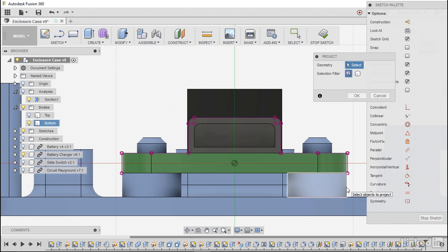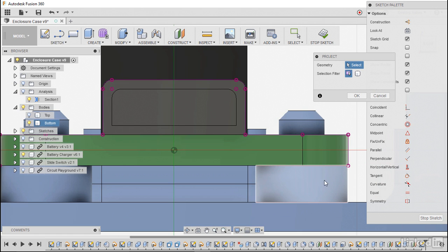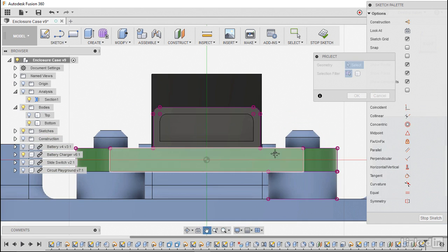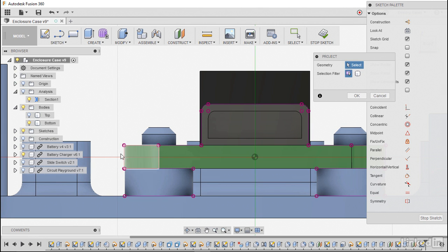Now when you get to this shape, because it's cylindrical, I can't select the edge, so we're actually going to have to select the face, which is okay. And that's actually another different approach you can take. If you're having problems selecting the edges, it's okay if you just select the faces. The only issue I'm trying to avoid there, it'll end up projecting all the 4 lines, for example, here that makes that shape. And so because we're going to do an offset onto this, it may make that part a little more complicated, because then we'll have to go and delete edges that we don't need. So that's why I'm just being careful just to select edges so we can skip deleting edges later.